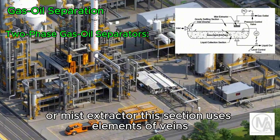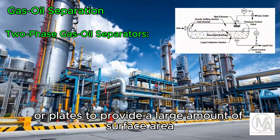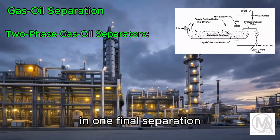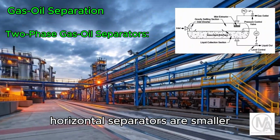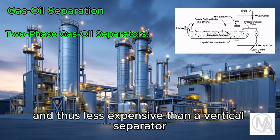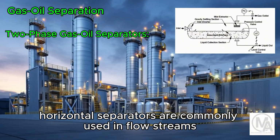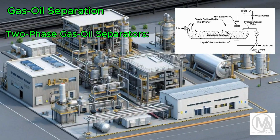This section uses elements of vanes, wire mesh, or plates to provide a large amount of surface area used to coalesce and remove the very small droplets of liquid in one final separation before the gas leaves the vessel. Horizontal separators are smaller and thus less expensive than a vertical separator for a given gas and liquid flow rate. Horizontal separators are commonly used in flow streams with high gas-liquid ratios and foaming crude.